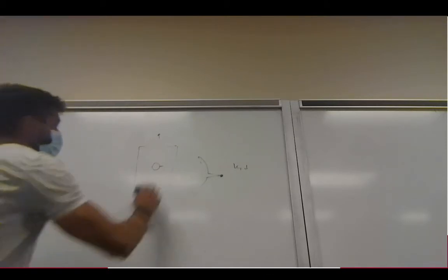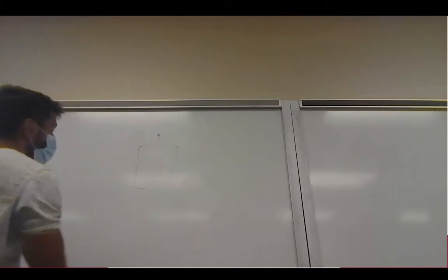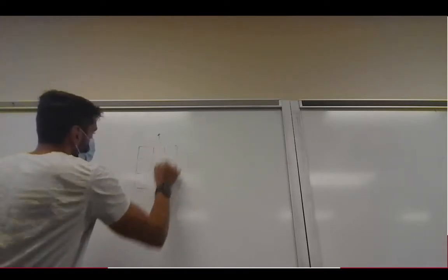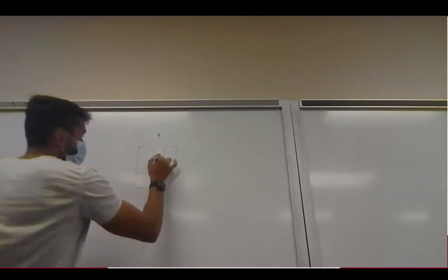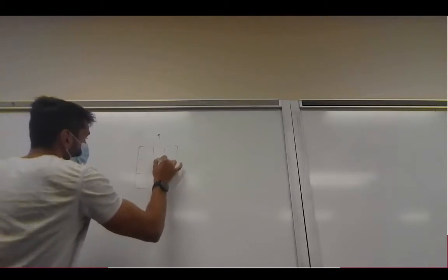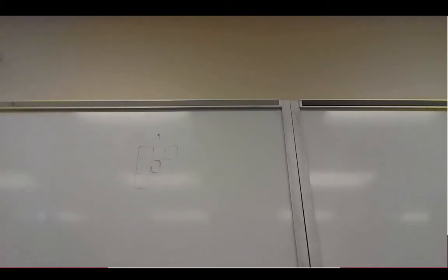So here what we're talking about is having a panel which is pristine, and then say we have a couple of stiffeners and stringers going through it, so they take up the normal forces, and we have a panel which basically has the shear flows. So again, in the panel, if we calculate the shear flow, they have to be in equilibrium within the panel itself.